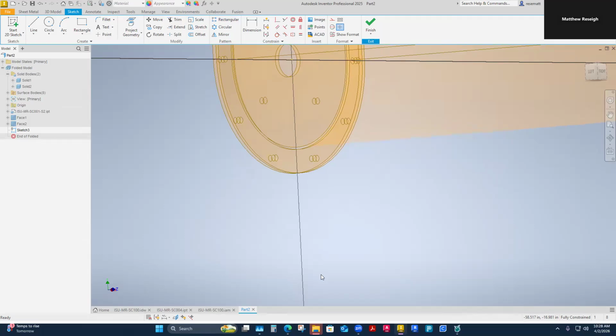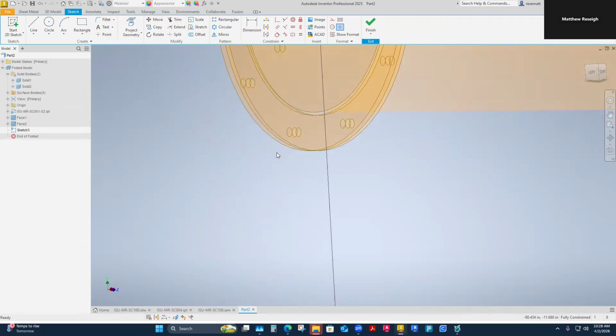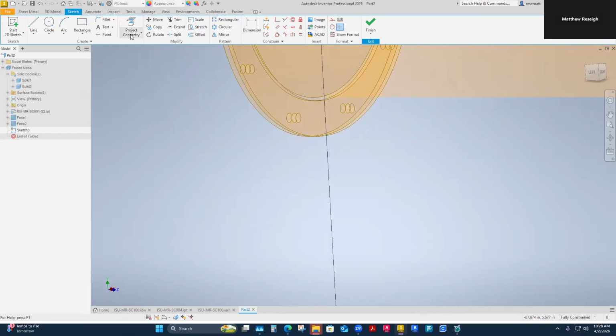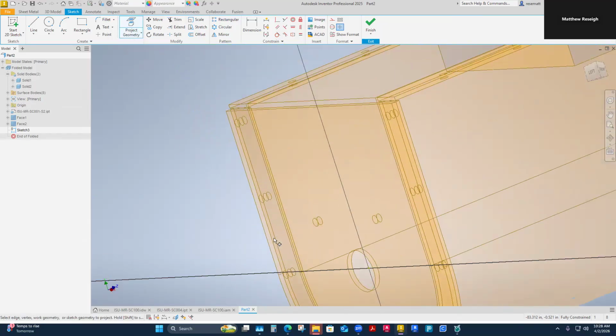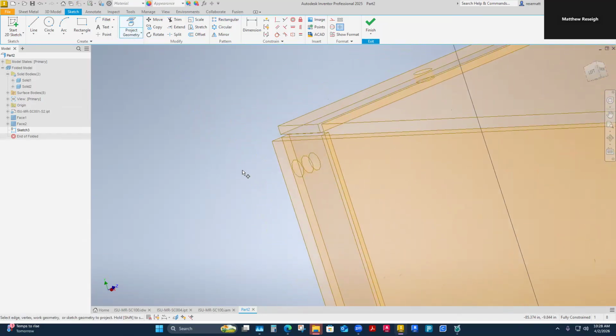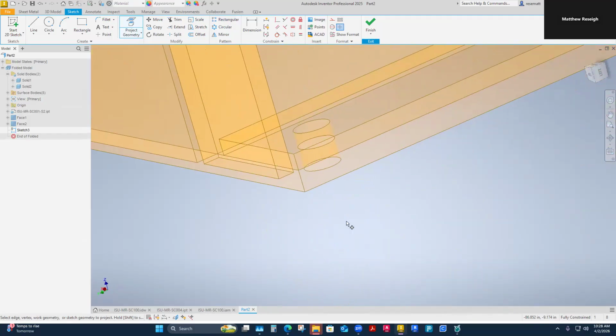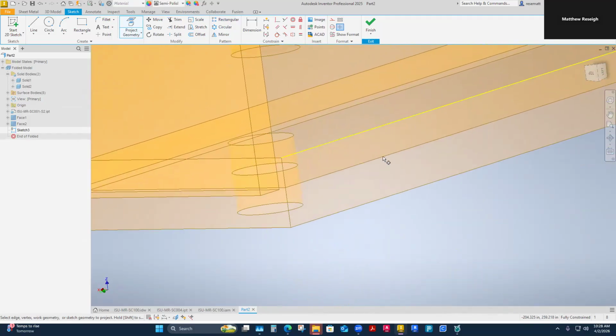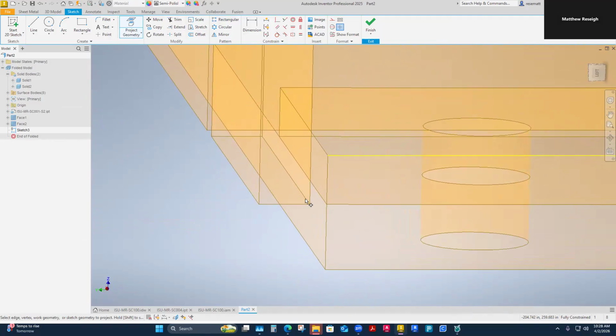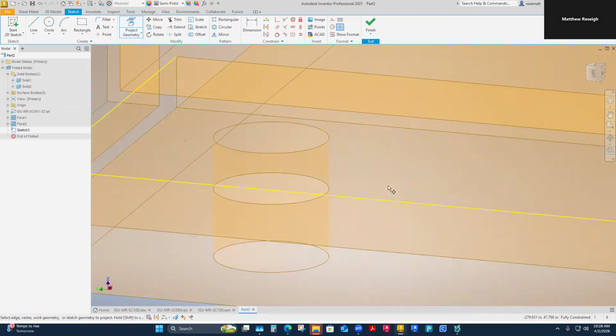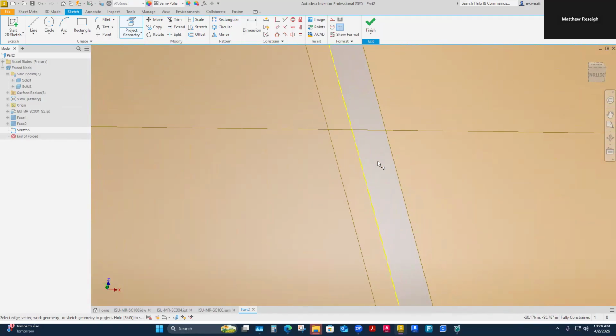And so I'm in the sketch mode. I'm sketching on this face, and then I'm just going to start projecting this geometry. And I tend to zoom in here, and I'm kind of picking the edges that are on that face. Like that's this edge, not this one. And over here, I'm zooming in. Yeah, I can zoom way in here, but I have no trouble selecting these. This is where you're having trouble selecting these.